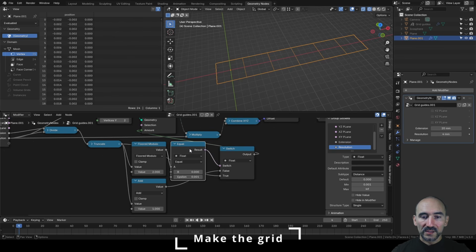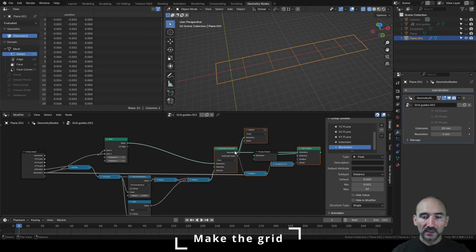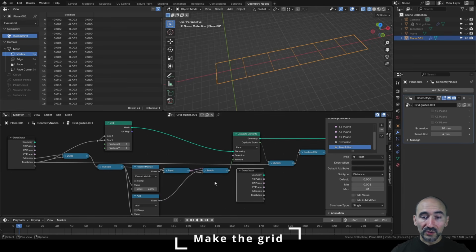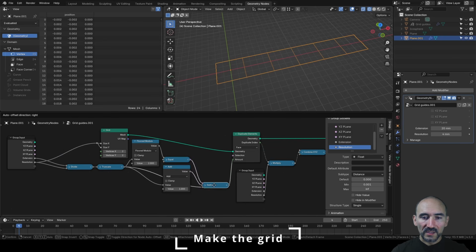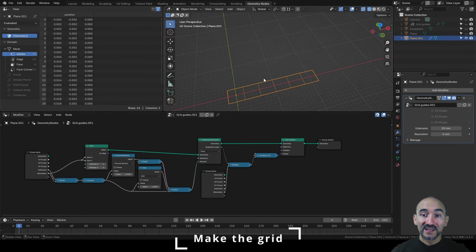Now I can press H to collapse these nodes. I can move these nodes a little bit. I can drop this viewer. I can add another time the group and link the resolution in this multiply like this, and now it is more clear. Now we can take this output and duplicate another time the faces, but going on the other axis, so the y-axis, to make the entire plane.